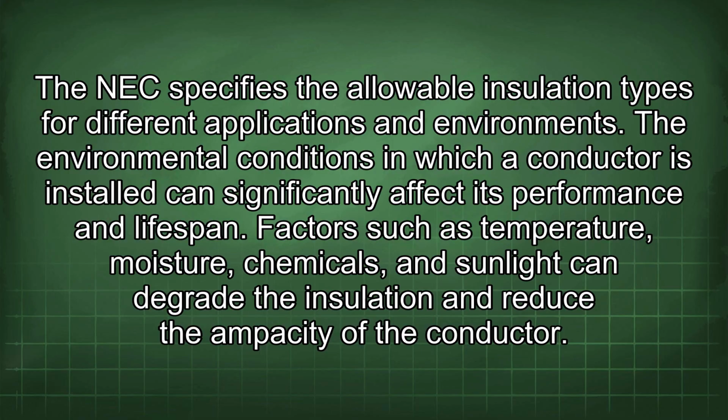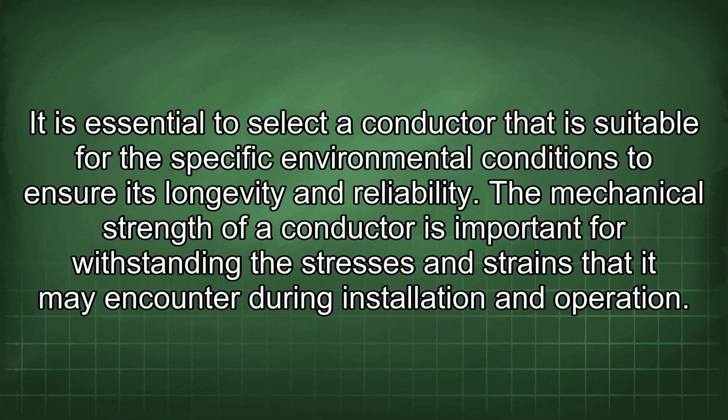The environmental conditions in which a conductor is installed can significantly affect its performance and lifespan. Factors such as temperature, moisture, chemicals, and sunlight can degrade the insulation and reduce the ampacity of the conductor. It is essential to select a conductor that is suitable for the specific environmental conditions to ensure its longevity and reliability.